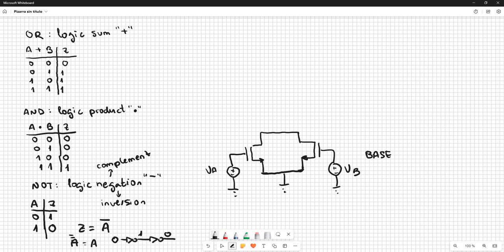and in the load, in the NMOS family, the load is going to be always an NMOS depletion MOSFET, in which we have always a channel. The channel is created in the manufacturing process, remember. The gate and the drain, the gate and the source are short circuited.